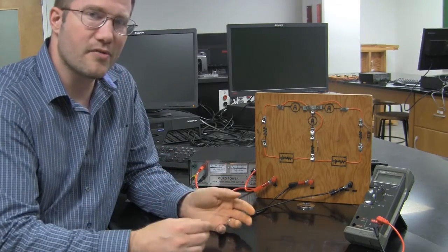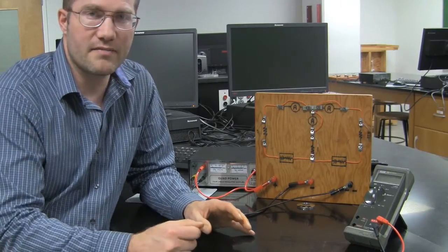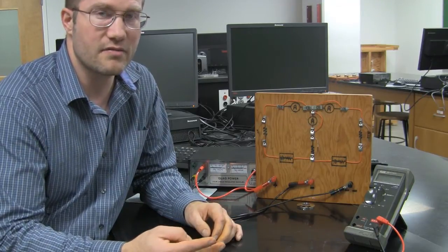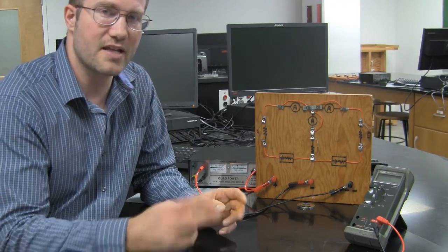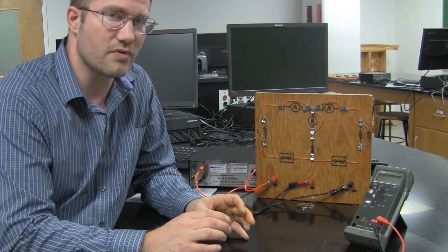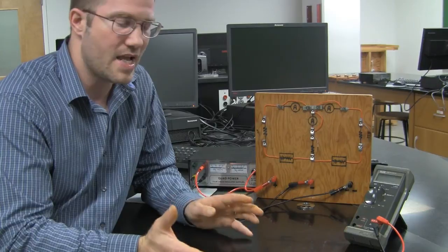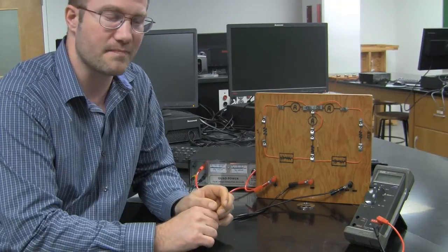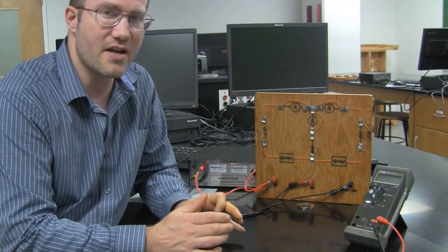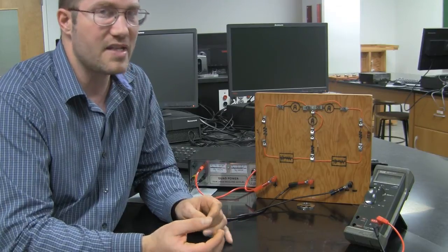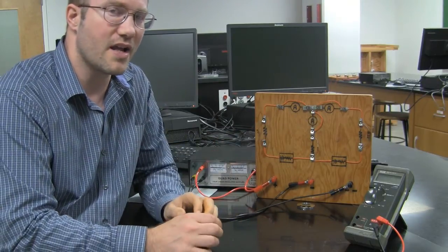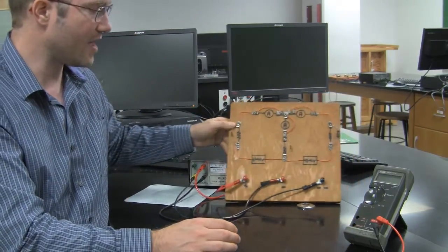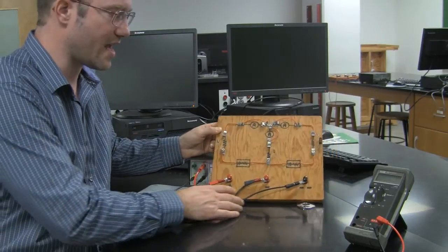So here I am back at the circuit board. Now, mathematically, I've gone through my two equations with two unknowns. I've solved for I1, I solved for I2, and then I took those two equations and I put them back into the Kirchhoff's current rule for junctions and solved for I3. And so now I've predicted mathematically my three currents, and it's time to come back over here to the board and test them. Now remember, if I got a negative value for a current in my calculations, that means that I assumed the wrong direction for the arrow. I haven't actually gone through the calculations, but let's assume that I have.